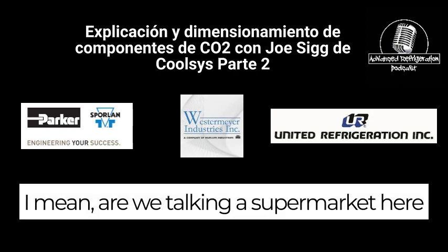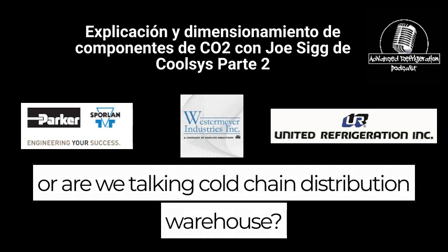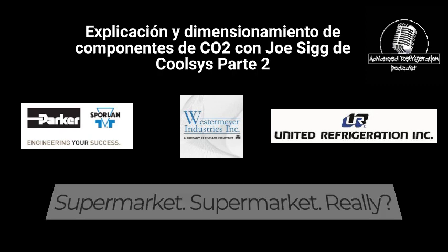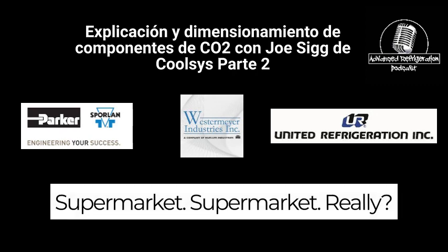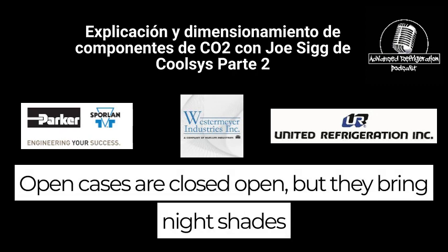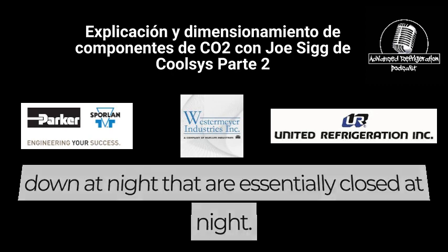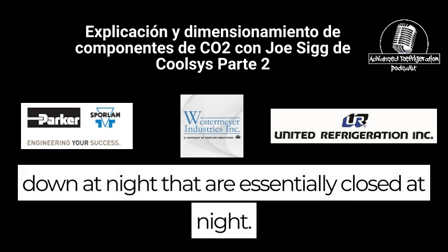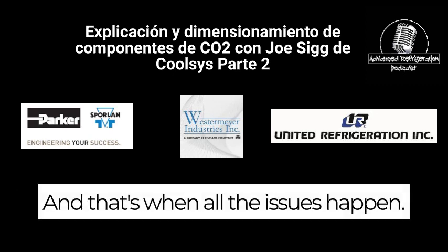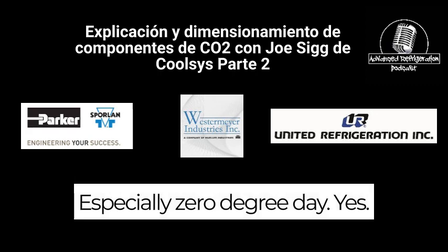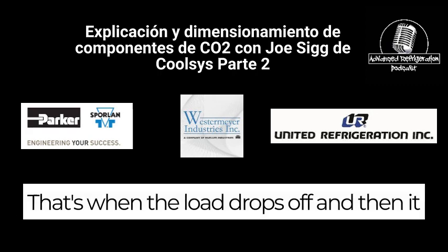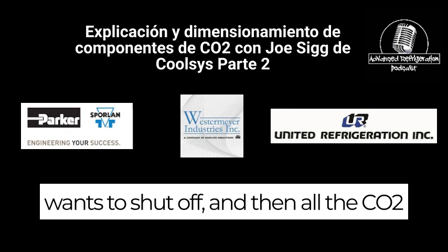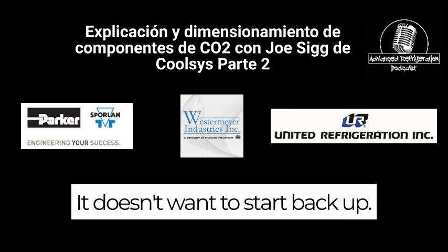Are we talking a supermarket here, or a cold chain distribution warehouse? Supermarket. Really? Open cases or closed? Open, but they bring night shades down at night, so they're essentially closed at night. Yeah, and that's when all the issues happen, especially on a 0-degree day. That's when the load drops off, and then it wants to shut off, and all the CO2 wants to sit in the gas cooler. It doesn't want to start back up.